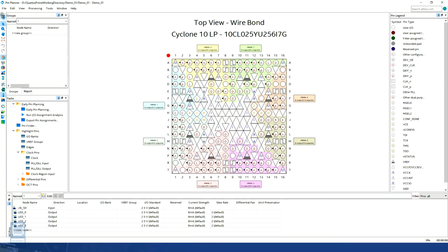All the panels are tagged and have a very definitive purpose. We encourage our viewers to go through them one by one and understand their functionality. For this example, we are going to focus on these All Pins and Main Preview panels. In the All Pins panel, we can see the pins we have declared in our schematic design file automatically imported here. This happened when we ran the analysis and elaboration task from the Quartus Prime main interface. If we hadn't run the analysis and elaboration task, then we would have had to enter these pins manually. We find this auto import feature convenient, but it's always a good idea to review them one more time before proceeding. Now we are ready to assign the locations to our pins.